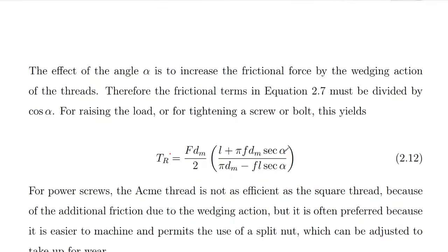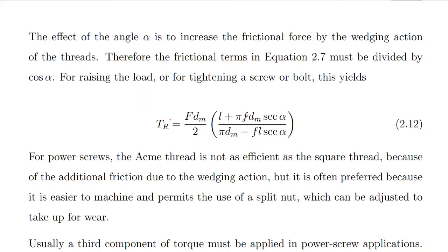So the friction terms become pi mu F d_m sec alpha, and pi mu F L sec alpha, which is the friction coefficient times the lead times sec alpha.